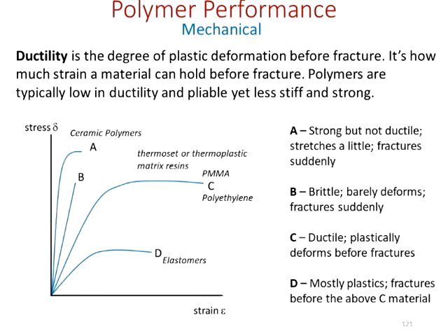So this gives an idea of where and what types of polymer might fall, generally speaking, into these categories. Again, this is not an ideally drawn diagram here. You could find more detail, but this gives you an idea of what the concepts to expect. So the types of polymers we're talking more about would be those thermosets and thermoplastic matrix resins, and matrix resin means that this is a compounded polymer.